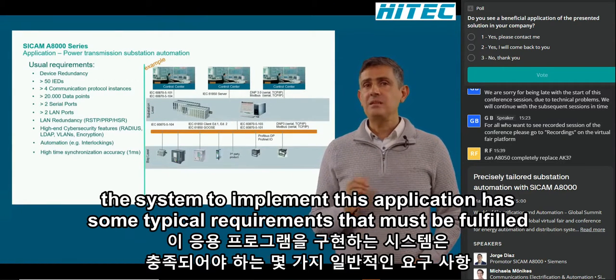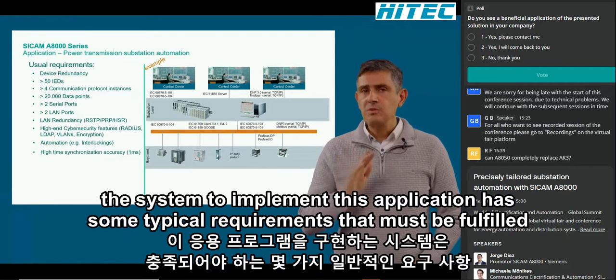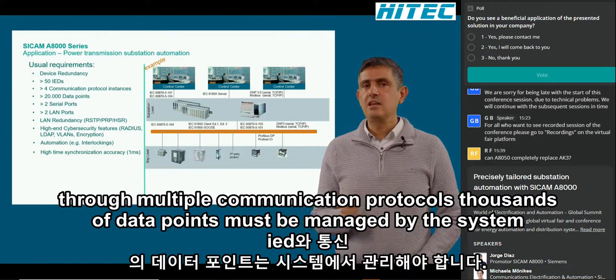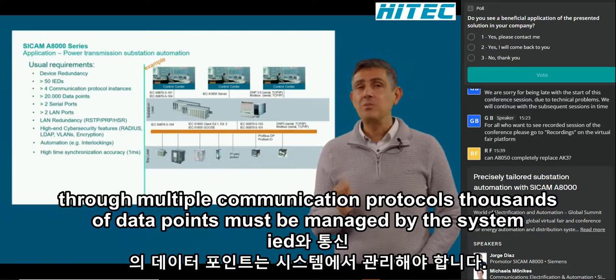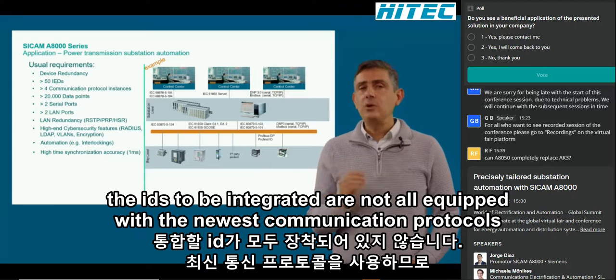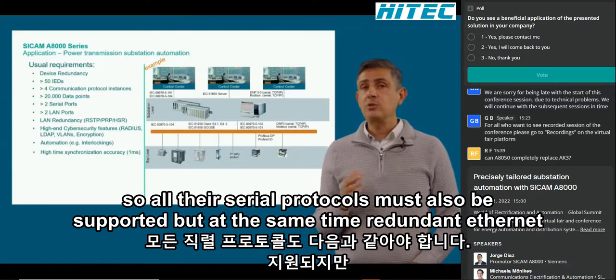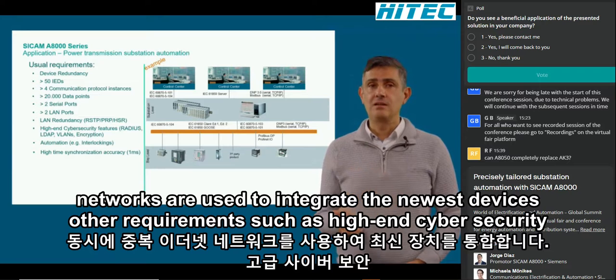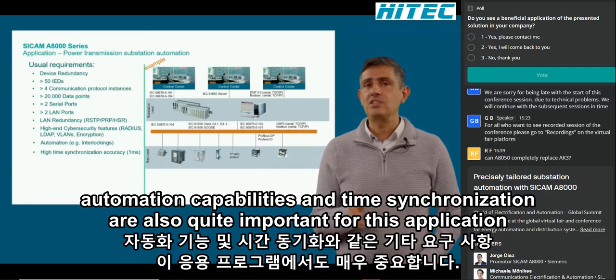The system to implement this application has some typical requirements that must be fulfilled. The system must be redundant, must communicate with several IEDs through multiple communication protocols. Thousands of data points must be managed by the system. The IEDs to be integrated are not all equipped with the newest communication protocols, so all their serial protocols must also be supported. But at the same time, redundant Ethernet networks are used to integrate the newest devices. Other requirements, such as high-end cybersecurity, automation capabilities, and time synchronization, are also quite important for this application.